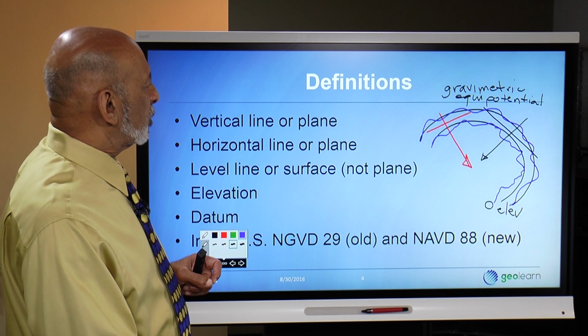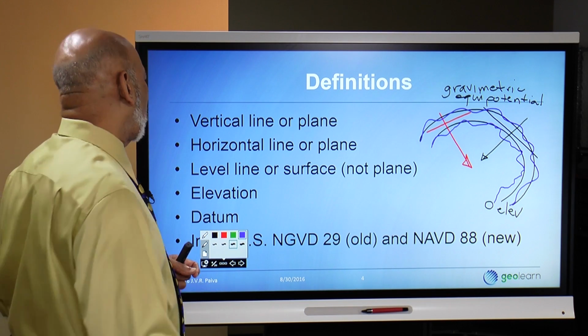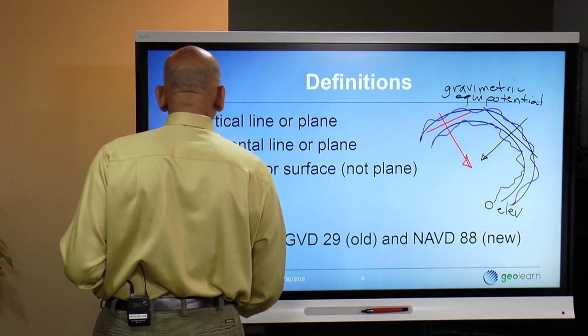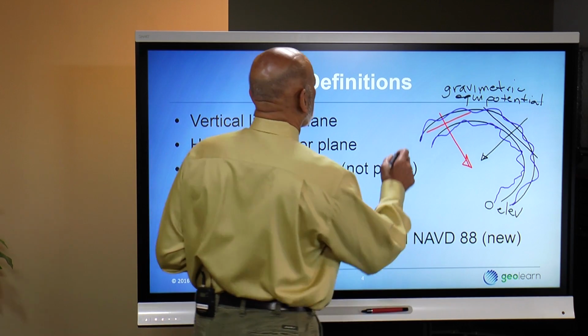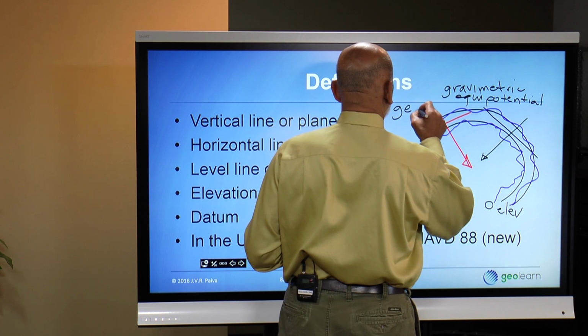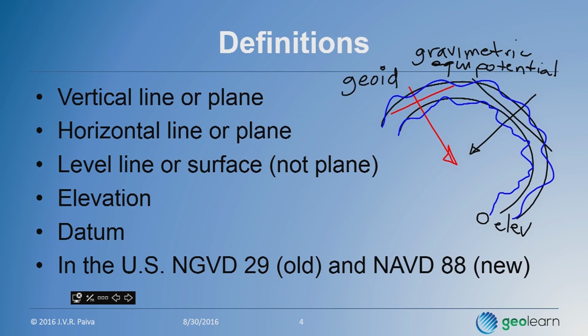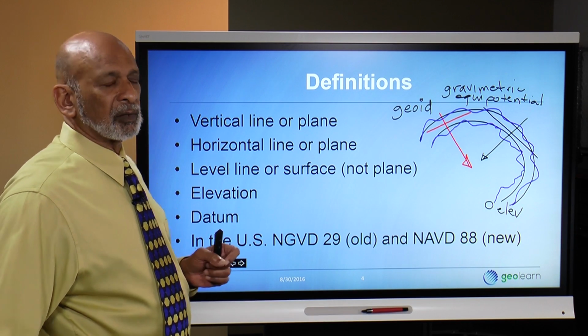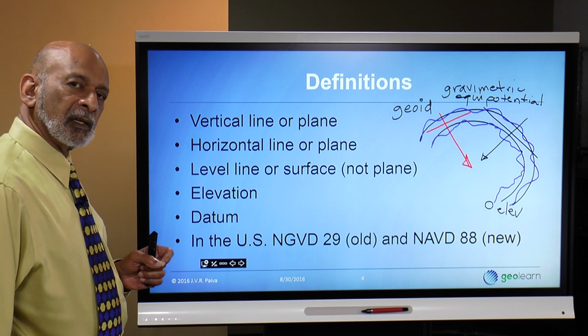And so this is where, when you get into doing especially GPS surveying, we'll talk about a concept known as the geoid. I'm just throwing this out for now here. Geoid basically relates to the gravimetric equipotential because GPS cannot determine elevations or differences in height using our system for determining what's up and down based on gravity. GPS does it a different way.